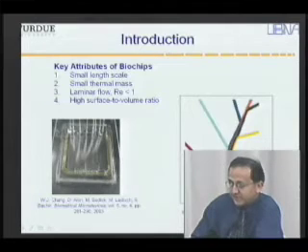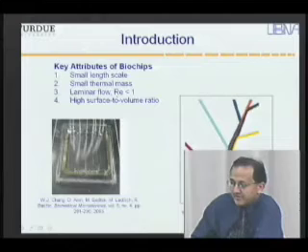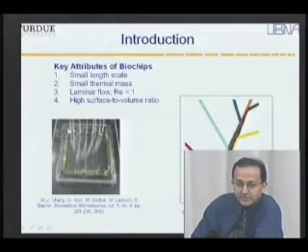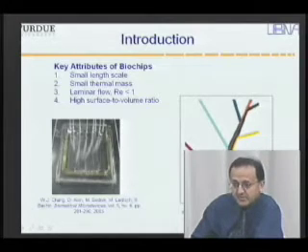At these scales, the fluid flow properties are unique, and more specifically there's a parameter called Reynolds number, and this Reynolds number ends up being about 1 or certainly less than 1 at these dimensions, and hence you get laminar flow. So it's actually pretty difficult to get turbulent flow or mixing in these devices. You have to take some special effort and go the extra mile to try to get mixing and turbulence.